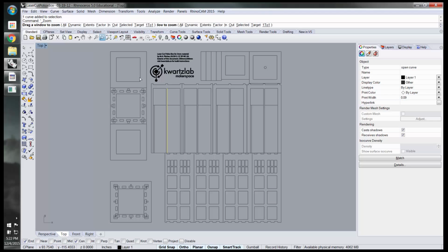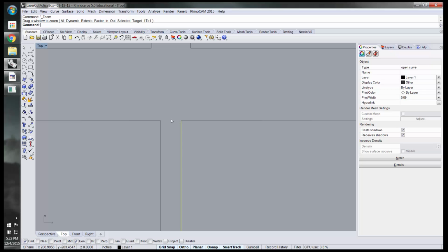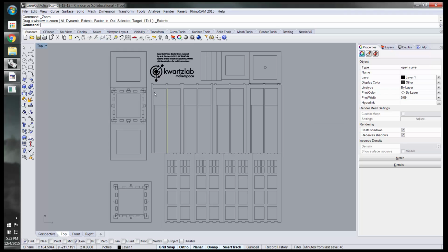Let's see what they've done here at the top. So that's pretty clean. I was wondering if these two were actually joined, but I think they were just grouped. So I would want to probably select these lines and group them together so that the laser makes one continuous pass around in a U shape like this, not run a line, stop, run a line. Remember, with vector sorting, it may cut this line and then move over here and cut a different line.